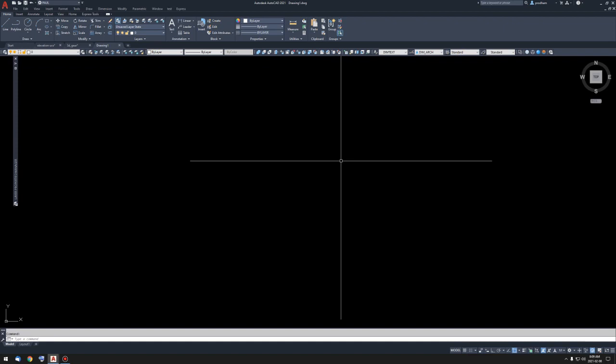So whether you're ready for this right now or you're not quite ready for it, you'll have this video to help walk you through the process. Now, the most important thing is that we want to use the power of XREFs. In theory, if we're working on a large project, we might have somebody drawing the elevations while I'm drawing the plans. So what we want to do is first of all XREF in the plans into our elevation drawing so that if anything changes on the plans, I will be notified while I'm drawing the elevations. So again, this would be great if you're working on a big project with other people and somebody says, hey, listen, Paul, I've updated the plans for your elevations. You might want to reload those XREFs so you can see the changes.